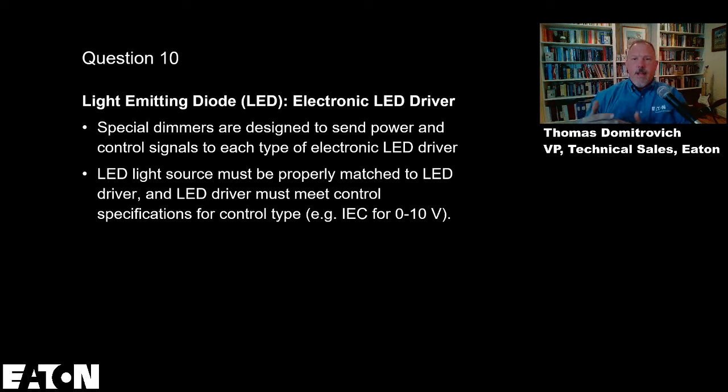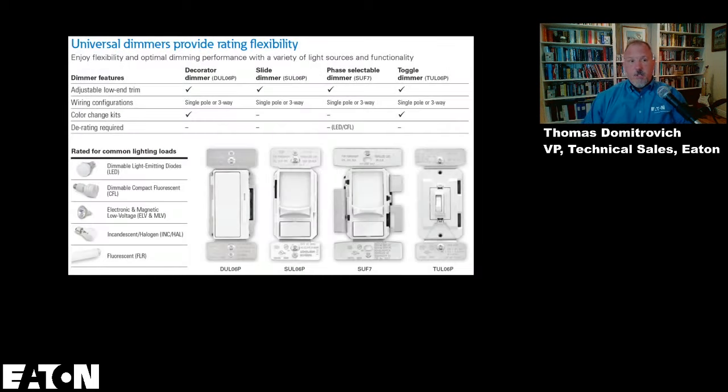I don't know if you've ever had this before. I know when I installed some of my lighting controllers, I think I had a dimmer switch. I had some LED lights and some fluorescent lights on the same circuit, and I started to get a pulse between them all. I ended up having to change my lights out all to one, and I think it was the compact fluorescents that were giving me the issue. I didn't change my dimmer switch, but I could have changed the dimmer switch to handle the loads as well. So you can end up running into some of those issues.